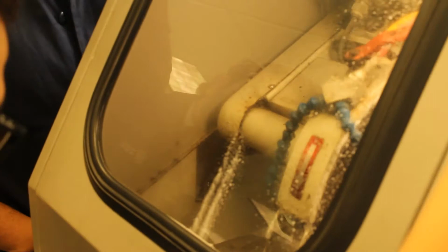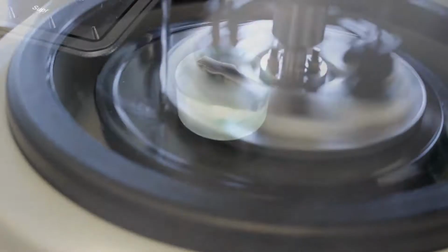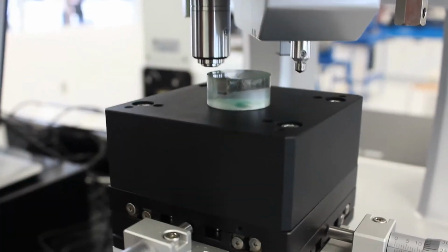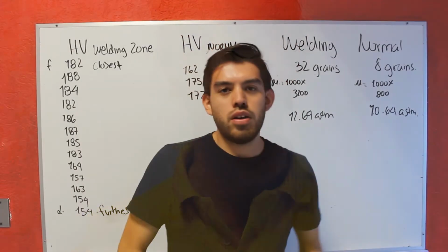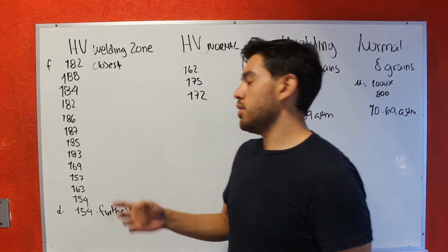During this practice, we first cut a metal plate into two, and then we did the welding process. Then we cut it into two small pieces in the cross section to be able to do the metallographic procedure, use a Vickers machine to do the microhardness test, and obtain all the micrographs.